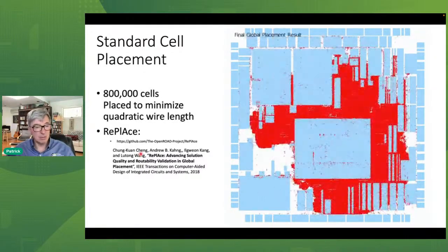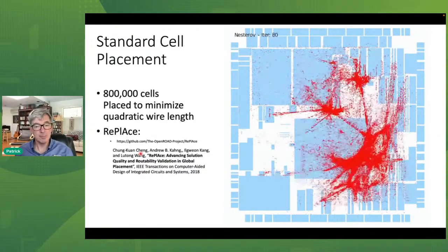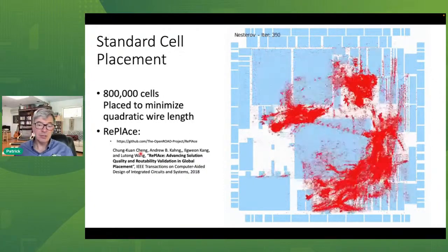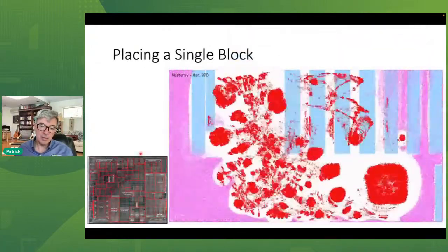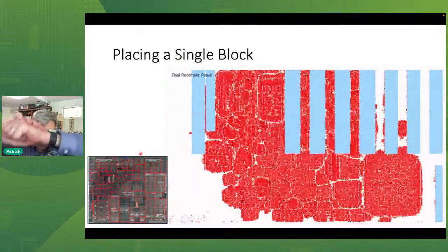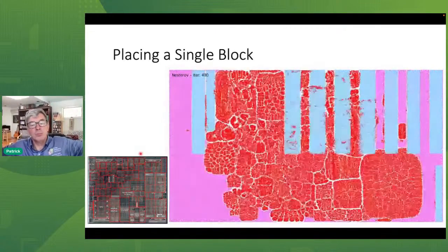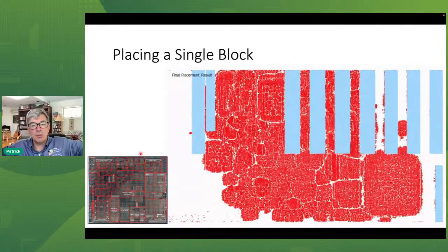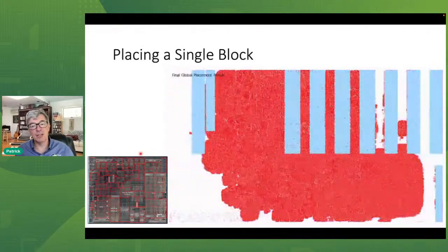This is the methodology roughly, with, okay, all kinds of modifications on why things work. Yeah, and this is a fairly complex example. If I look at the block like this, it's fairly similar. Yeah, so initially they're all clustered together, then we push them apart, and they slowly go to a still minimal wire length configuration in between the cells that optimizes total wire lengths.